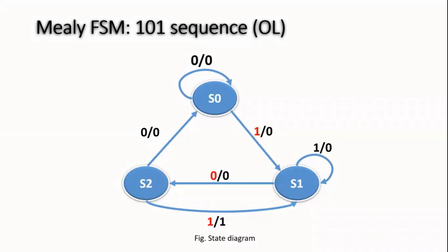Right. Now we are entering into a problem. Now the task is that we are going to come up with an FSM, design the FSM, write the code, and test it for this sequence. Say for example, let's do here. I have been asked to come up with an FSM design for detecting the value 101. Right? So what am I supposed to do? Let me first start with a single state.